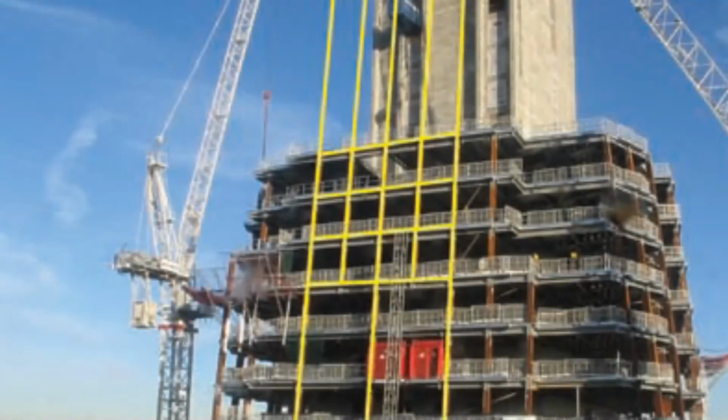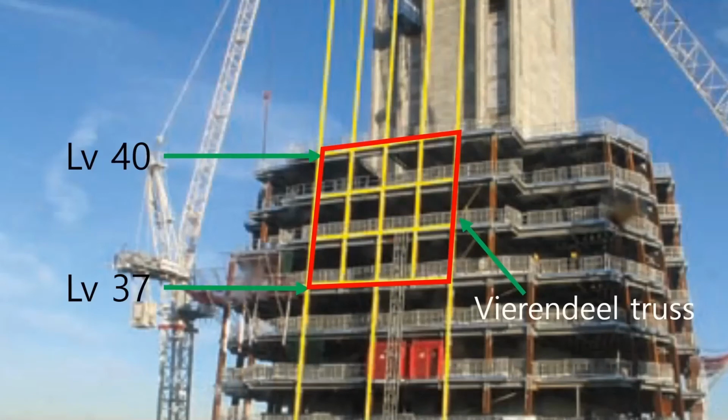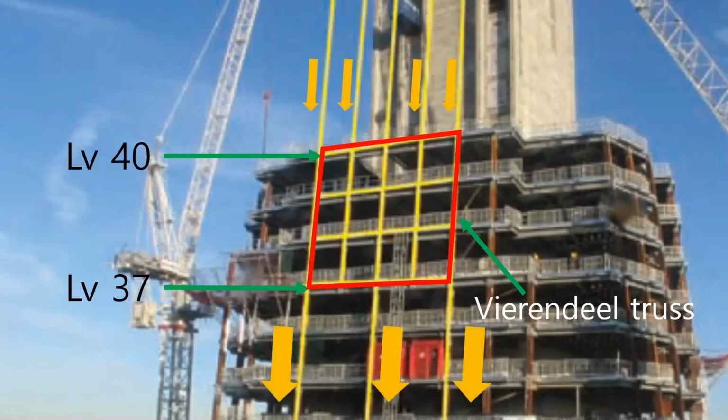Engineers found a solution to connect these two different columns. As the solution, in levels 37 to 40, the top of the steel levels, a blended truss changes the span of the perimeter column from 6 meters to 3 meters.